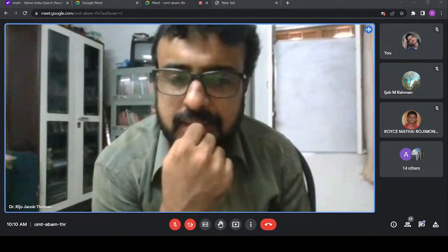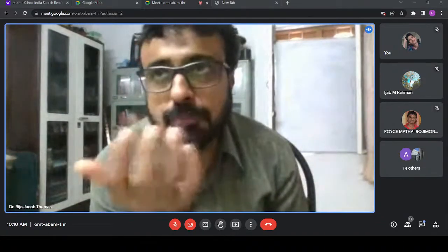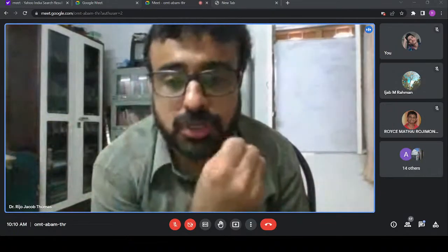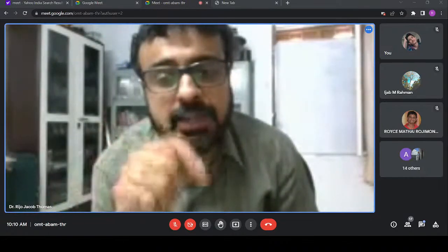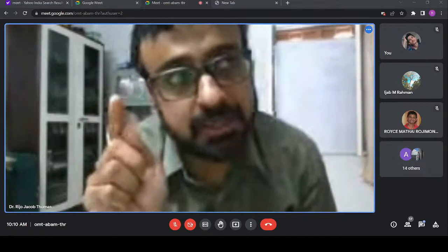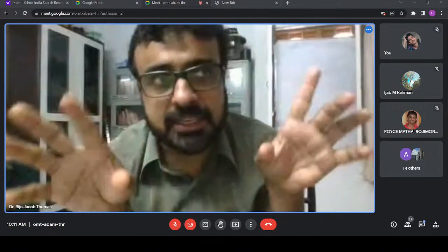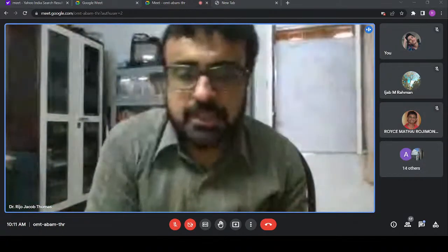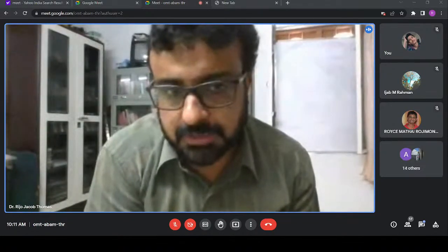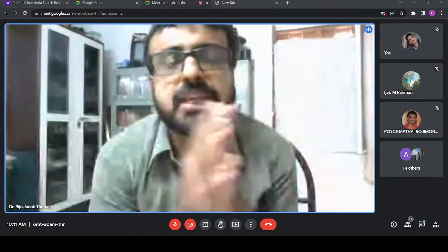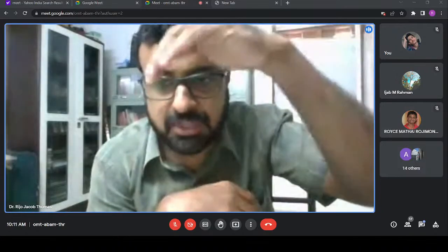But this is again a factor. If you come into this gas turbine and all, there is the mass flow rate of the air, and when the mass flow rate is varied, this air fuel ratio also varies accordingly. Okay, how much it should be. So there is actually a region where you can operate. That is sometimes called your stability loop. It's a range between rich and weak limits. They say the rich area and the weak area.